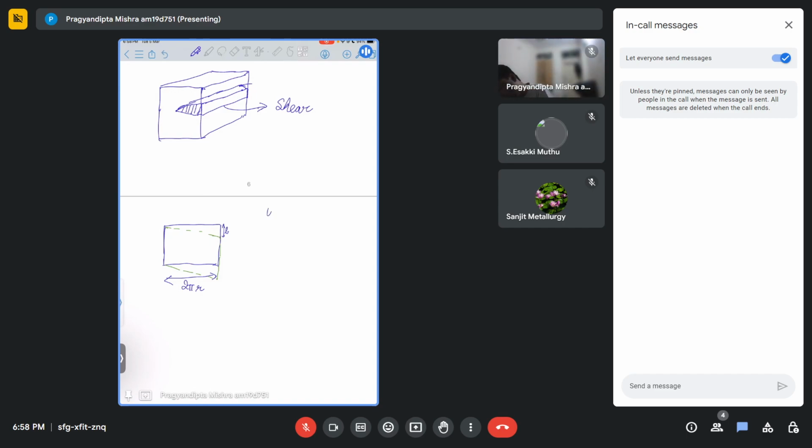Now I know along the x direction, or along the y direction also, for a screw we will not have any deformation. So those things will be 0. But along the z direction, I can write some theta by which this turn has happened times the radius, theta r, as my new value by which this 2 pi r has rotated.